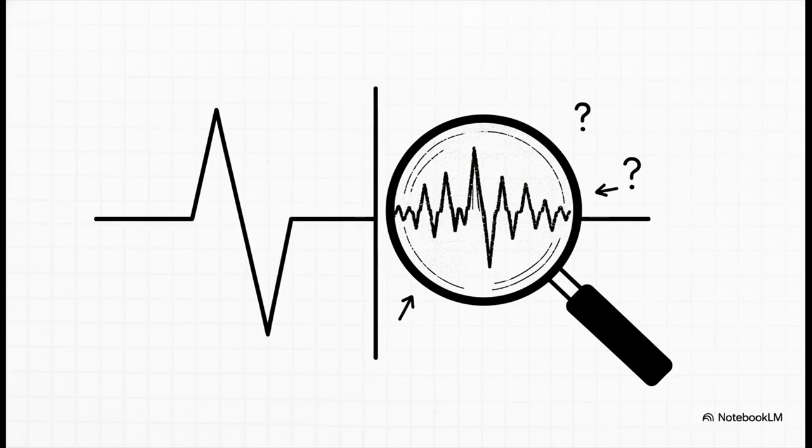Also, rather than relying on arbitrary blanket rules for your frequencies, you need to analyze your actual signal characteristics. Sure, pure DC doesn't couple like AC does, but digital switching noise absolutely rides on those DC supply lines. Try using the simple pulse rise time formula. That's 1 over pi times tau. This little equation uncovers the hidden high-frequency components that are secretly lurking in your data lines. Even a seemingly super slow 64 kilobit per second data line can contain incredibly aggressive 10 MHz noise components if the edge rate is sharp enough. The big takeaway? Analyze the rise time, not just the data rate.